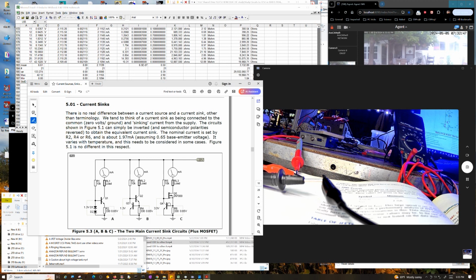It's self-balancing, and the same thing kind of applies to the FET. You've got the same transistor circuit here doing the same thing. This is still responsible for setting the current, but instead of starving it of current like it's doing over here, it's starving it of voltage. So it tends to regulate the voltage of the FET, which causes the current to either increase or decrease. So it's able to adjust itself to do that as well.